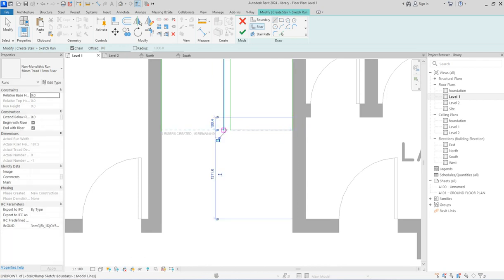Remember, this is a public building, so the most important thing is that the footpath should be more than 300. So what we do here is that we're going to use a footpath of 350. So click this and then you say footpath 350. 350 footpaths. Let's select that.